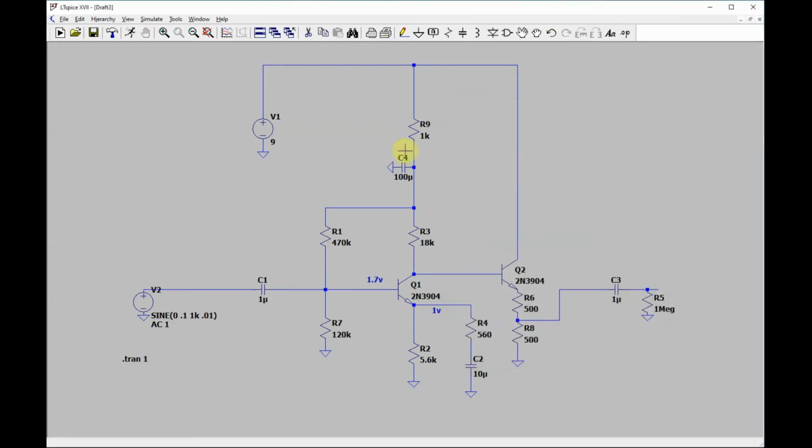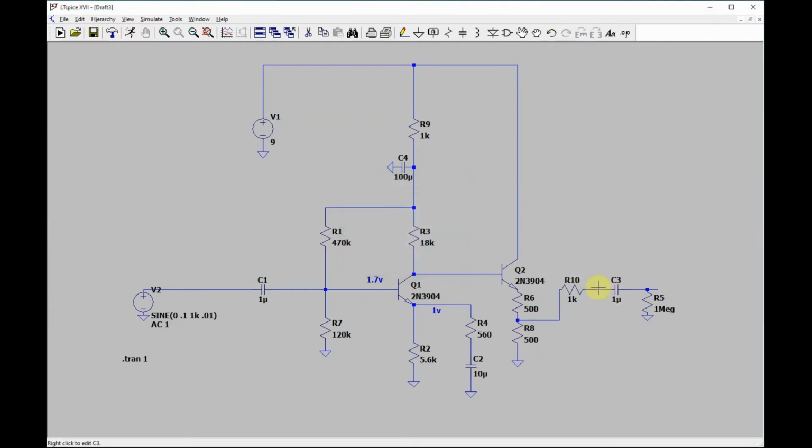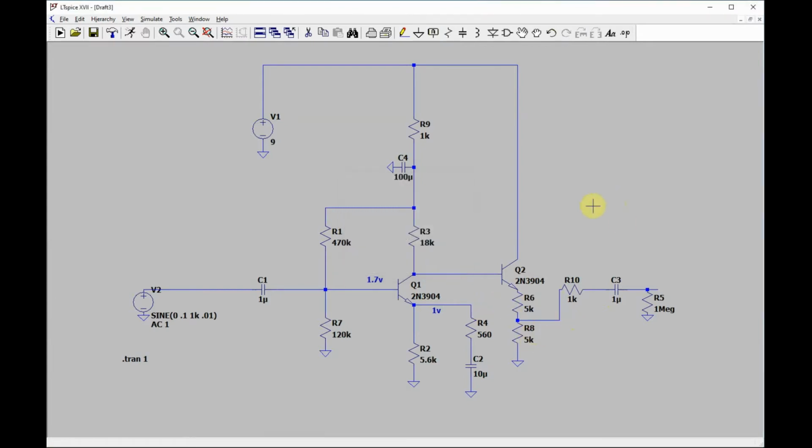So you'd use an electrolytic capacitor there, I suppose. And this would help filter out noise and prevent oscillations. I think I mentioned in another video, I usually use a little series resistor there of some sort. Honestly, I'll just make it more realistic. I wouldn't really use 1K there usually. So this is kind of the design you can use.